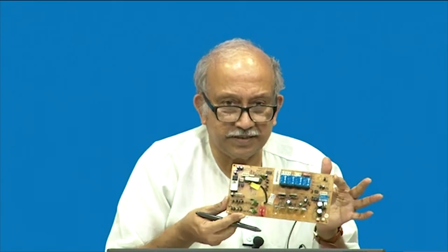In the case of our little larger things, wherever a current of more than 1 amp is involved and you have large electromechanical devices, this is a bank of relays, and it says, of course, 7 amps. 7 amps is not DC breaking, neither is it a service rating, it is just some nominal rating, and the person uses it, he knows what to do with it, but it can safely carry 7 amps.